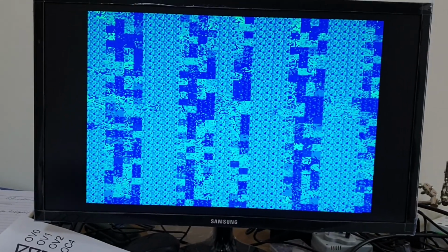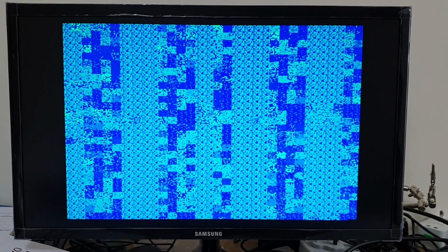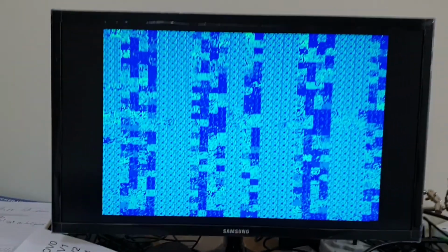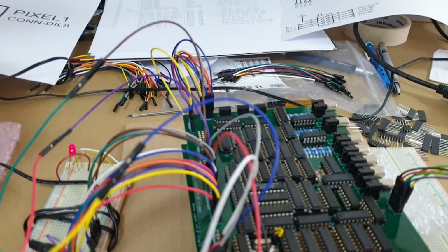So I've set up the data bus to be FFE character, so 3FFE. At the moment the character is the same as the contention. If I then press the other button, which brings the memory enable write line low, now it's written a different character to the top left. So you can see when I switch between the contention 3FF and now it's showing 3FE, because the character in the top left hand corner of the screen has changed. That indicates to me that the memory writing logic, at least for that location, 9040, is actually working correctly.